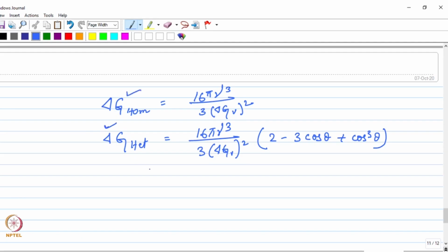And as a result of that, when you have heterogeneous nucleation sites, more number of nuclei can easily form compared to the homogeneous case, right? So that is how you get a higher nucleation rate also in case of the heterogeneous nucleation.